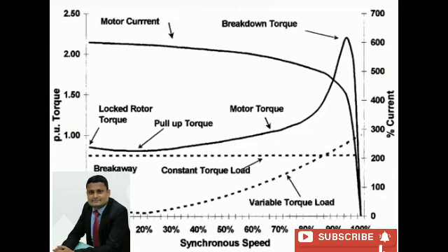So ATP' equals AT' into Ss by P. So flux density at 1/3 height in teeth, that is BT' equals flux per pole divided by total tooth area per pole at 1/3 height. So BT' equals phi by ATP'.